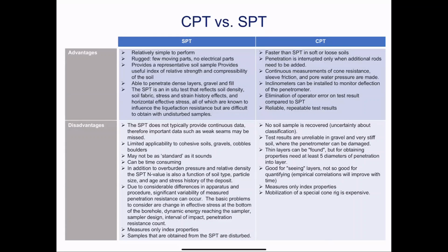Last but not least, for SPT, we mentioned, although you get samples, they're highly disturbed. For CPT, you're in a lot of trouble for very strong frictional material, gravel or very stiff clay. Mobilization of CPT is slightly more expensive. You have to have a rig, a barge, and since it's not as common as SPT testing, you need a specialist operator to conduct tests, and this can be more expensive.